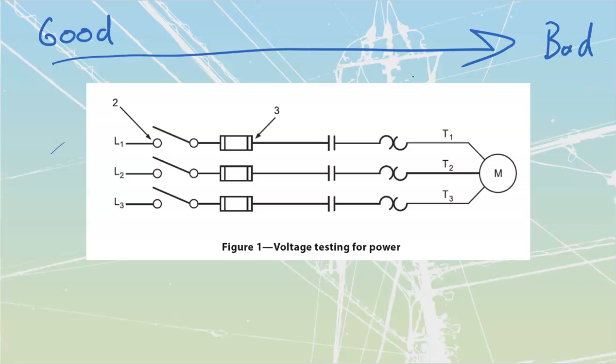Usually we're going to find that either we have lost protection, something has been operated, P&C, as far as our breakers, fuses, overloads, switches, etc., where something designed to operate is shutting it off. Or we're going to find that we are not making a complete circuit because something has failed. Stuff has burnt open, it's been damaged, we've lost a connection. Or we have proper connections and proper components, but it's an actual load problem. So one of those three is what we can expect to see.